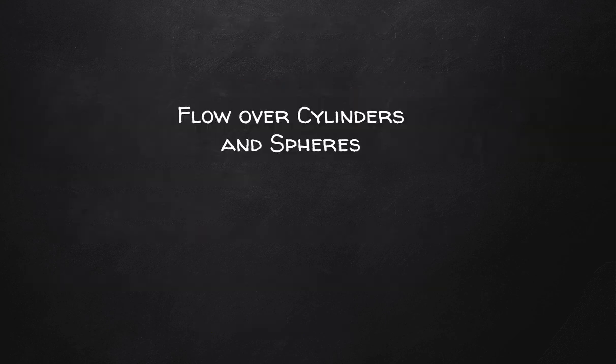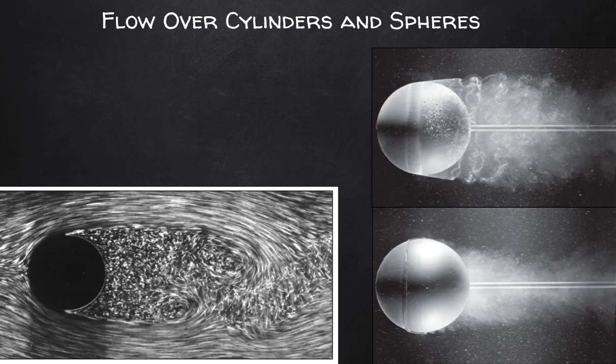Now, the last case that we want to get into is for external forced convection that will entail flow across cylinders as well as for spheres. Why spheres? Well, sometimes we have a reactor, chemical reactor, where we have flow that goes past spherical catalyst beads or larger beads of a graphite encased uranium. And also cylinders, well, because shell and tube heat exchangers are designed based on pipes. So let's first have a look at the case for the sphere.